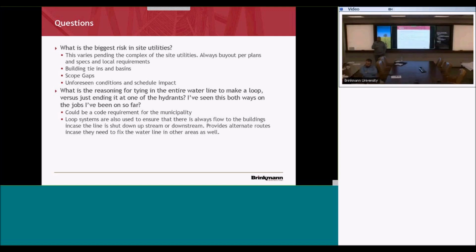Anything else? Unit cost advisors? I got one. We talk a lot about making sure you understand the water pressure at the street and everything, but you kind of hit on it, the gas pressure too. Generally, if you have a new building and a new feed, the gas company's telling you that and you have a pretty good feel for it, but on our renovation in Louisville, the engineer told us we had 2 PSI. We found out after we blew all the regulators that it was 15. And so don't just trust it. It's probably worth the money to test it to really find out the gas pressure too.